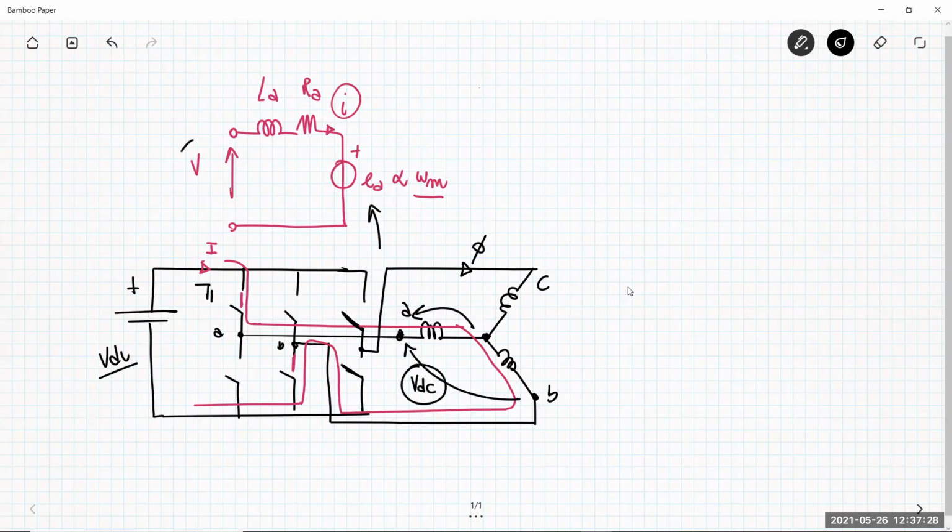I have to modulate V, the voltage that I supply to any phases, in order to control the operating speed of my BLDC motor. In that situation, I have just constant voltage. So typically, what is done is to apply pulse width modulation techniques, by which I can use as supplying voltage for my phases an average value, which depends on a duty cycle.